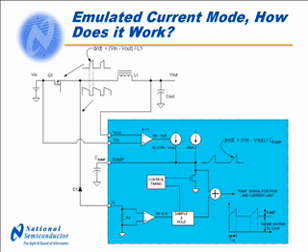If we set the value of this ramp capacitor proportional to the inductor value, we can scale the capacitor voltage to match the ramping current signal. The final step is to add the sample and hold of the diode current level to the capacitor ramp voltage. Now we have recreated the buck switch signal with no delays and no leading edge noise spike. We can now use this signal for pulse width modulation and current limit purposes as in conventional current mode control. Each period after the buck switch turns off, the ramp capacitor is discharged in preparation for the next cycle.